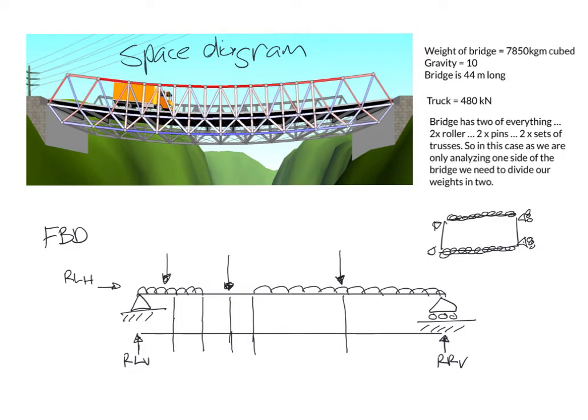What I'm getting at here is that these weights are for the total of the bridge. What we are doing at the moment, we can calculate the totals, which is fine. However, later on, we're going to have to divide it by 2 in this circumstance because we're only working on half of the bridge. Now in the HSC, you're not going to get a question like this, but I'm trying to tie this back to real life. These calculations that we're doing will be based on half of the bridge, especially when we start doing the method of joints and the method of sectioning.